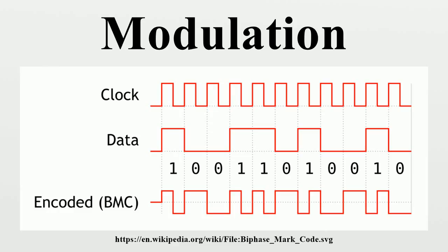Sometimes this is achieved using DSP technology, for example direct digital synthesis using a waveform table, instead of analog signal processing. In that case the above DAC step should be done after this step. Amplification and analog band pass filtering to avoid harmonic distortion and periodic spectrum.